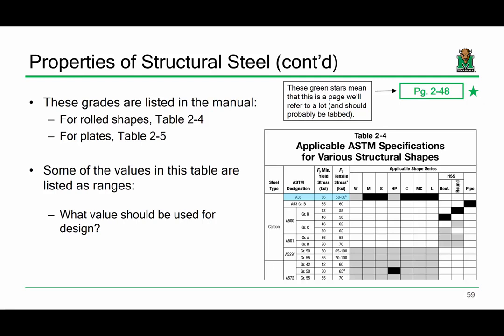What happened in Northridge was that some of the moment frames that the steel industry thought were fine and were going to perform beautifully under earthquakes experienced a lot of cracking. It wasn't the end of the world, because ultimately there were no fatalities. But the issue was we thought it was going to be fine, and they weren't. So what happened? In short, the larger your FU, the lower your ductility. So we were assuming all this ductility, and we really didn't get it.